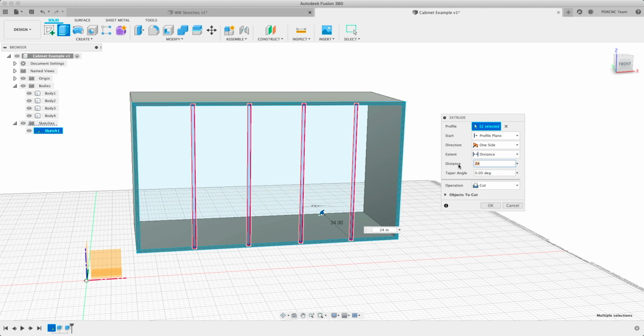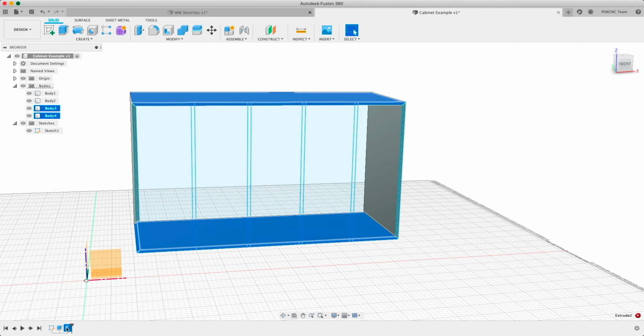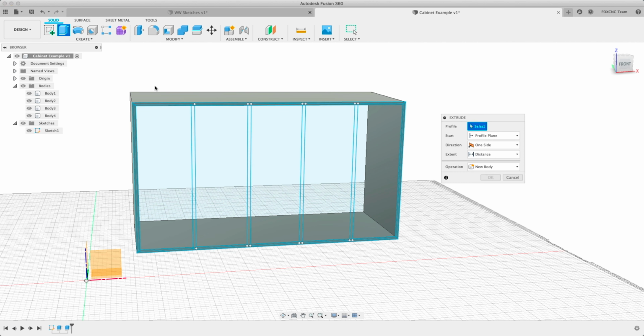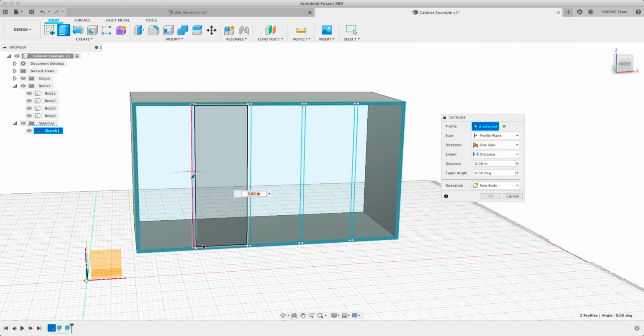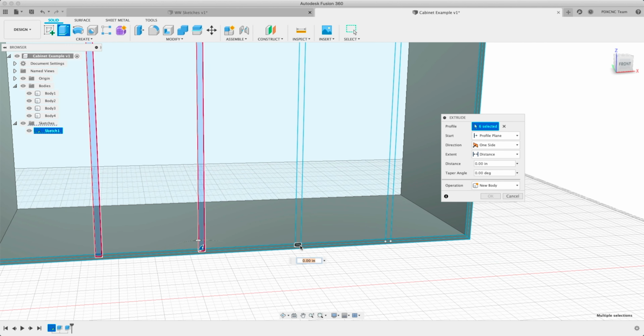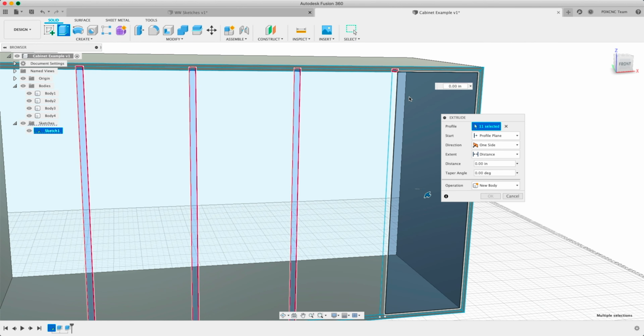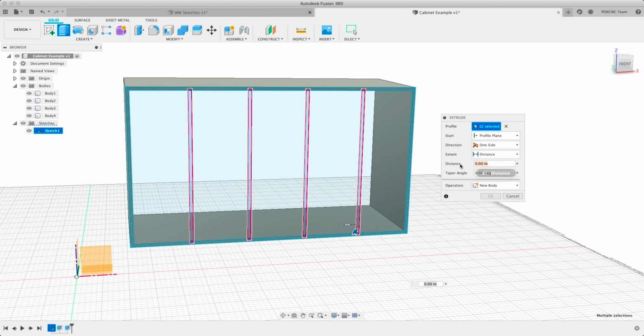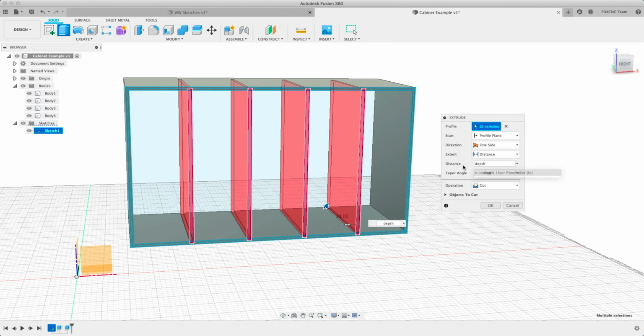So we want to extrude those to the depth parameter again, which is the same as typing 24, but this is better. Type depth. Depth doesn't work for some reason. Extrude. Make all my selections again. I don't know what happened there. If you accidentally select the wrong thing, you can hold Control or Command and get rid of it with that selection again. Let's try this again.